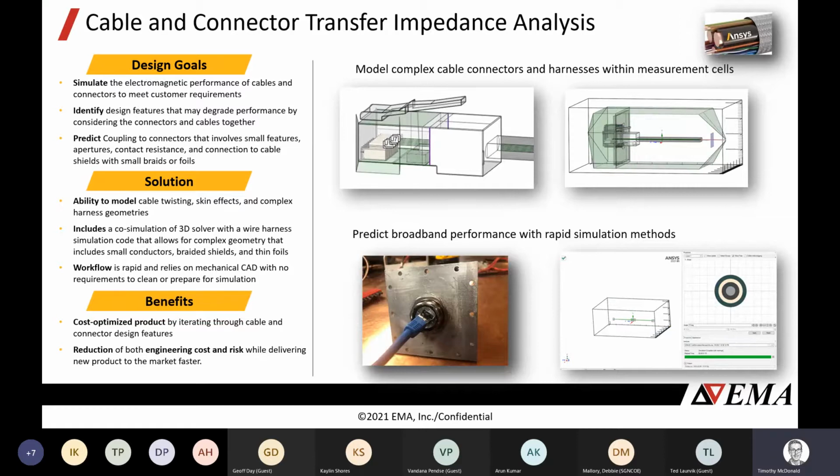And as we talked about before, the way that transfer impedance helps our program at the vehicle level is that it allows us to parameterize the transfer impedance through a submodel or measurement and apply that at the vehicle level so that it takes us less time to build the overall model. If we do one submodel for one style of connector, we can use the resulting transfer impedance metric over and over again without having to rerun that simulation in the full vehicle simulation. We can save ourselves time.